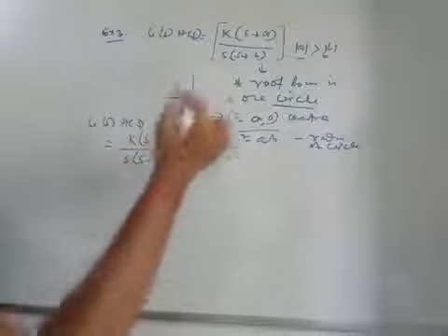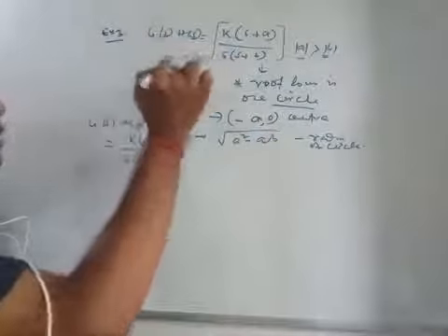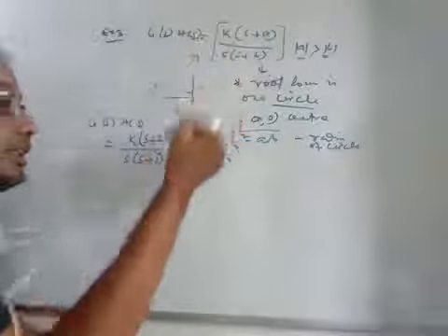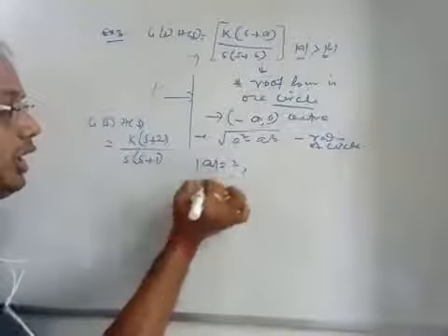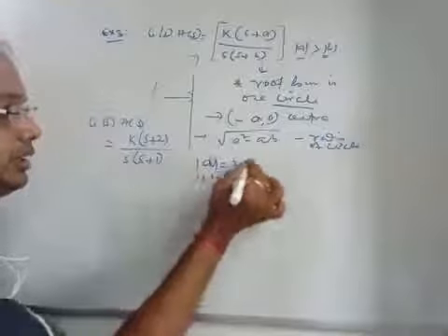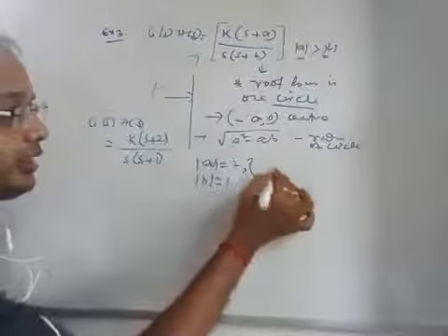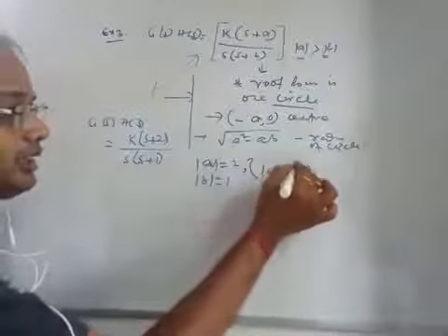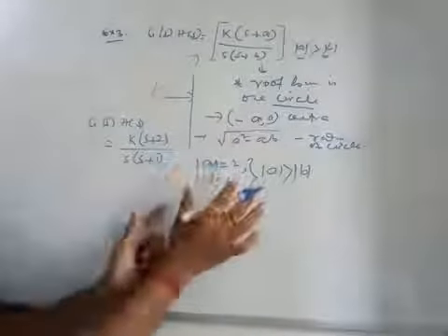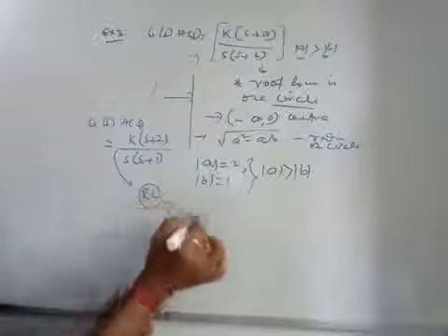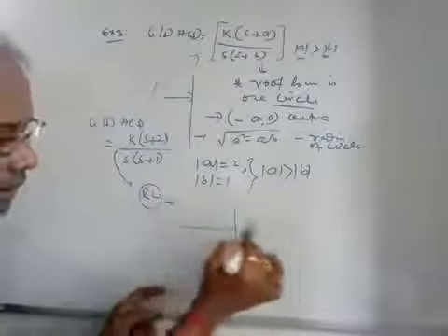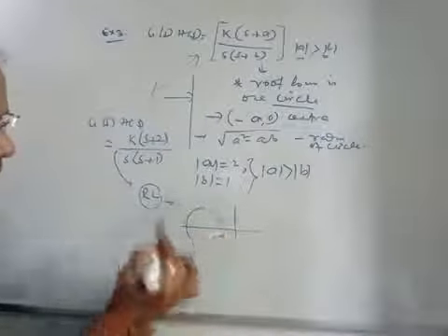By the similarity between these two functions, as this is a standard one, you can see modulus of a is equal to 2 and modulus of b is equal to 1. So this condition is satisfied. That means mod of a is greater than mod of b. If this condition is satisfied, then the root locus corresponding to this system will be like a circle, right?